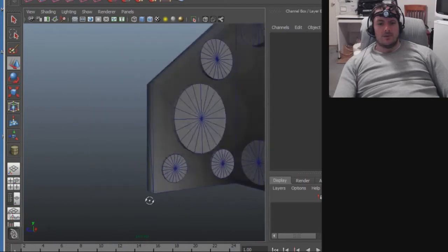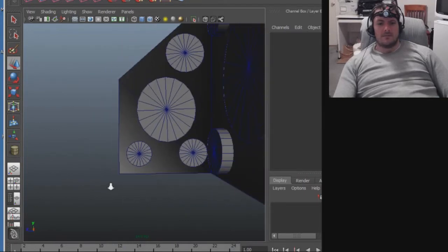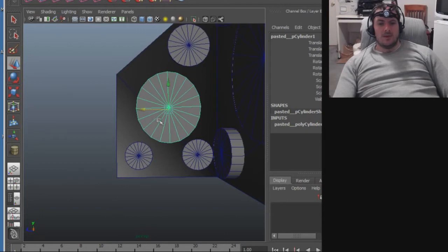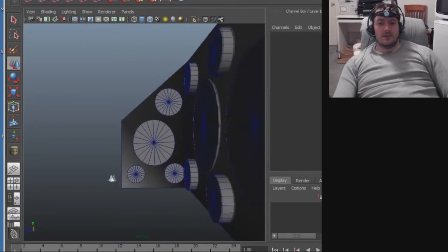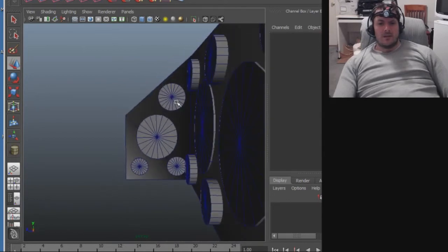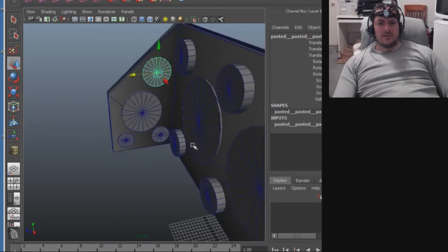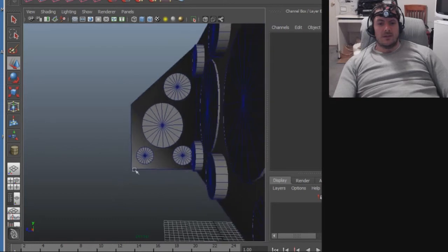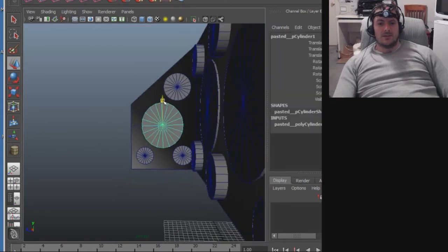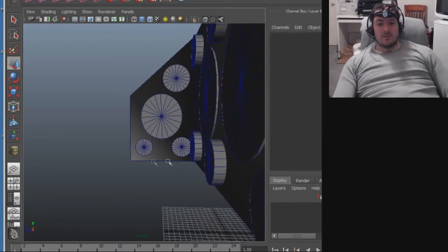And that way when the print prints, each layer will have relief of the stresses that that layer wants to create to rip the print into a warped shape. Each layer is like the string of a bow and arrow, and it wants to rip up the layer below it. And with each layer, those strings get tauter and tauter. They're like rubber bands, and they'll rip up the bottom and tear it all up.